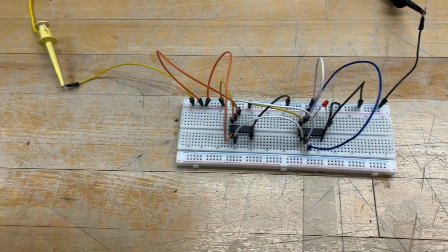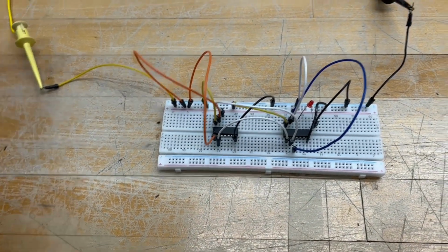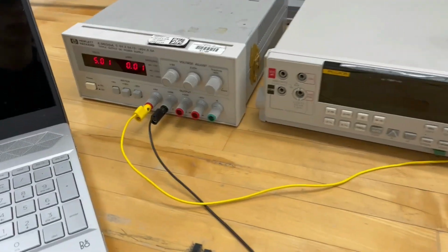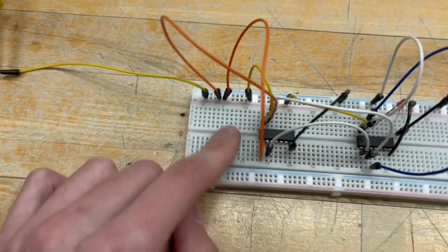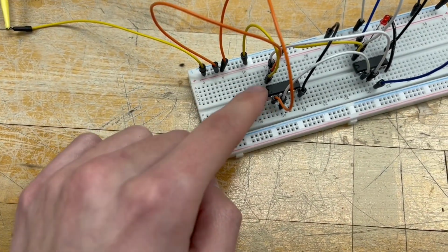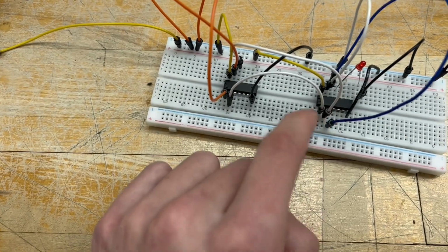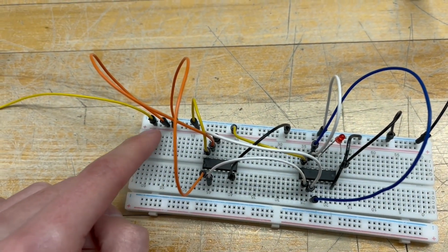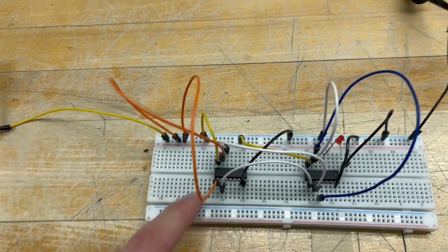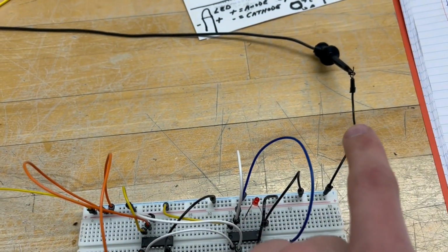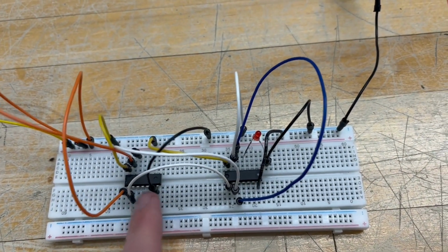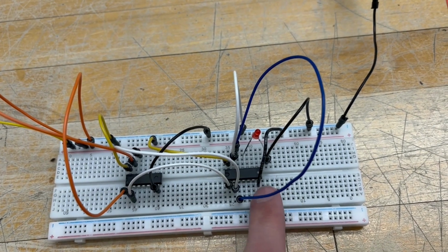I will now be walking through and testing the circuit. Our yellow wire going in here is our 5 volts coming from the 5-volt source. The yellow wires are the VCCs for both gates. There you go into the positive node with the 5 volts. Black is grounded, that's our ground wire, and black wires were used to ground the gates as well.